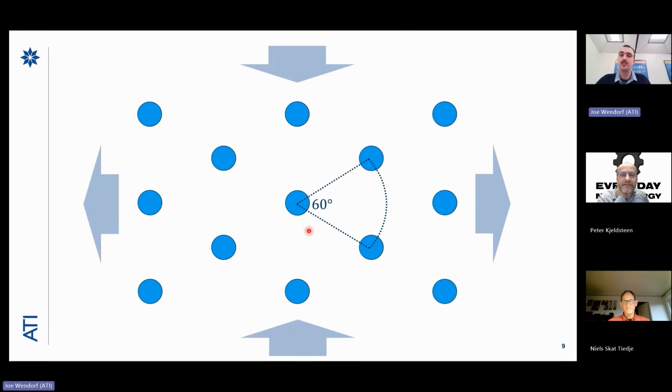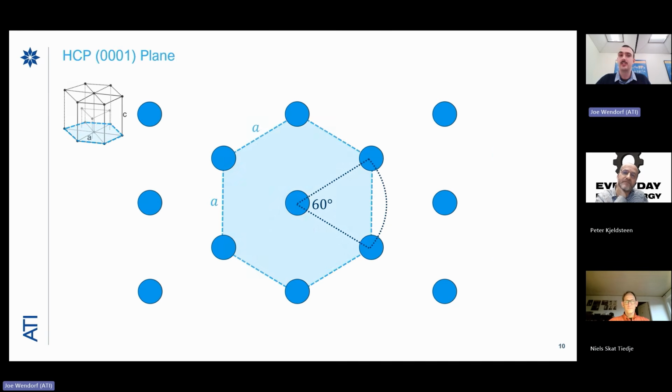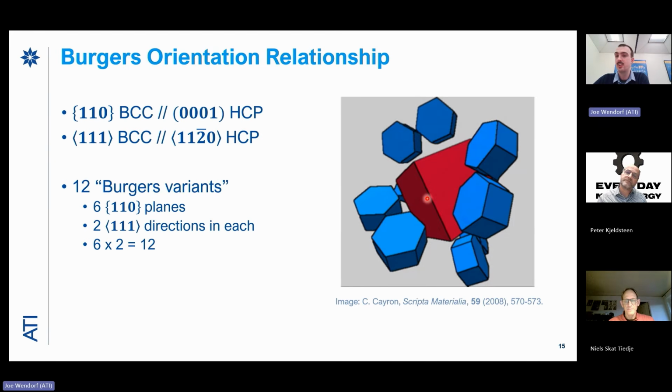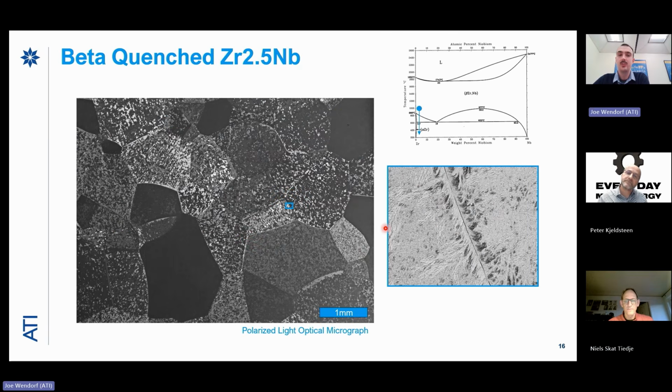And now, if you look at this deformed BCC crystal, this is an HCP crystal structure. Because there's this really precise orientation relationship, you can actually see with your eyes, we call them prior beta grains, they have all of these different orientations, sometimes with a similar reflectivity.